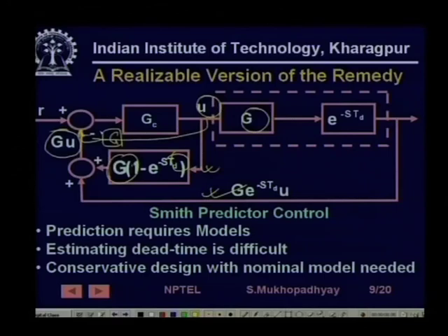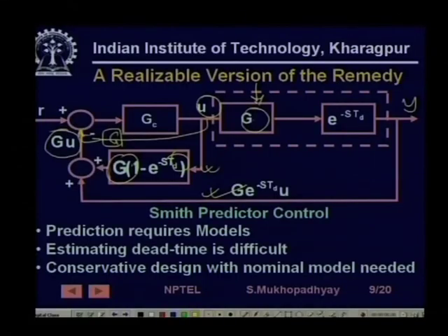But what do we get then? Then we get what is known as open loop control. There is no feedback. What are the problems of open loop control? That any error in G will directly affect the output Y. Any disturbance here will not get corrected. The biggest advantage of feedback control is that it gives you performance generally irrespective of, of course you have to know certain things, but small modeling errors do not affect performance. That is the single reason for which feedback control is used.